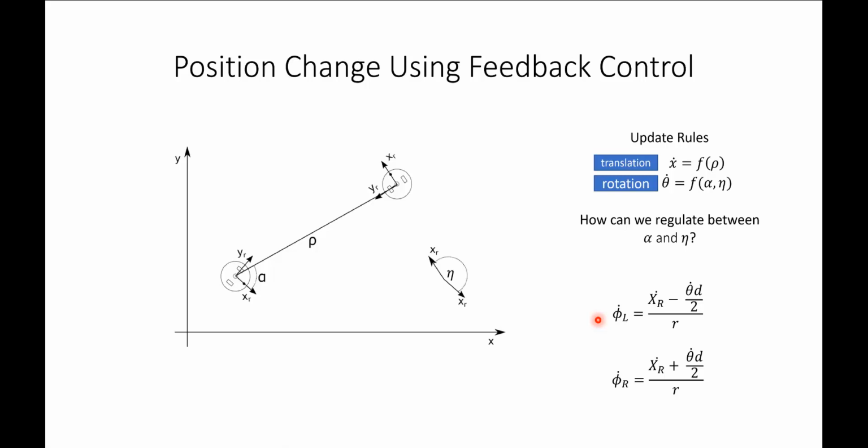So whatever the ratio there is, you're going to go that proportion of whatever you want your robot's maximum speed to be, and that's how you're going to get your robot to get from one position to another using these inverse kinematics equations. So you're essentially just setting up a feedback controller, and you are getting closer and closer, 32 milliseconds at a time, until you hit some kind of stopping criteria.